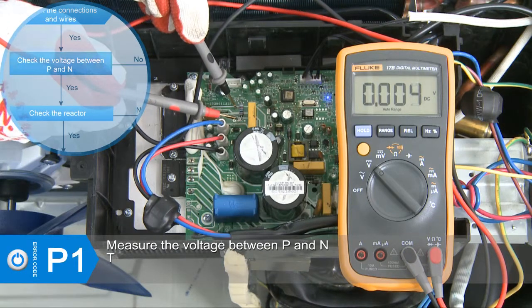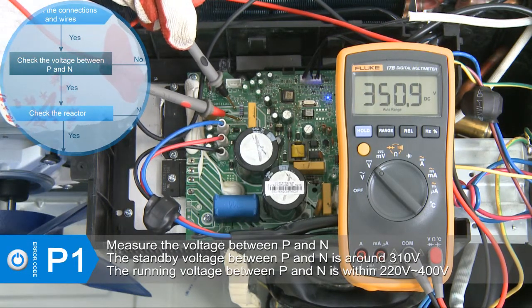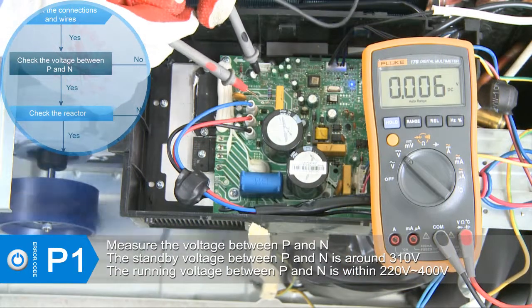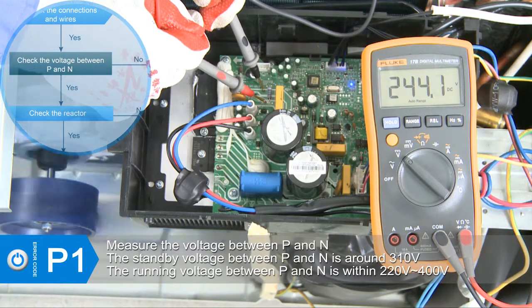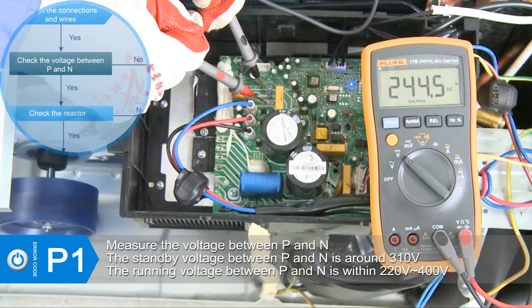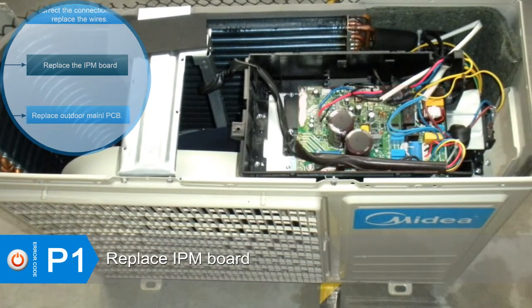After confirming that the wire is good, when the unit is in standby mode, check if the voltage between P and N is around 310 volts. Then start up the unit. Measure the voltage between P and N and see if it's within 220 volts to 400 volts. If the voltage is abnormal, replace the IPM board.